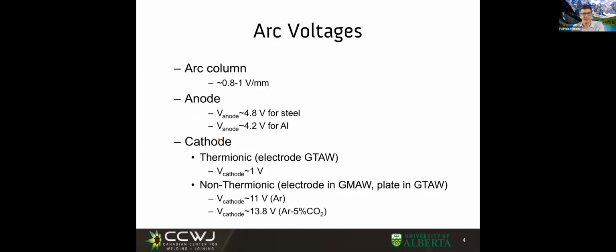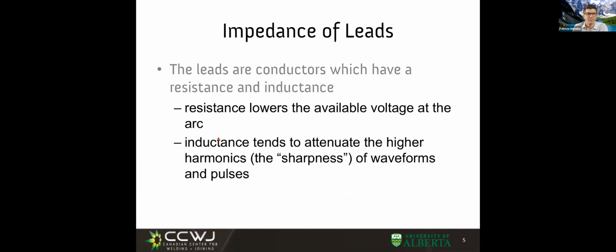We'll use these numbers soon. Let's talk about resistance of the cable. So the cables have, instead of resistance, we should use the proper name, impedance. Impedance is kind of fancy for resistance, but the difference matters, because resistance is a term that relates to constant current. But if I have pulsing, then I have all kinds of electromagnetic effects, right?